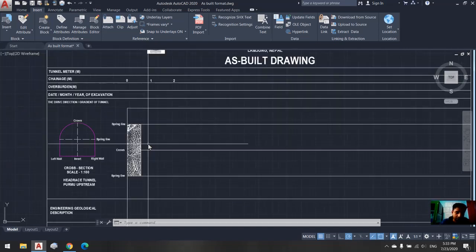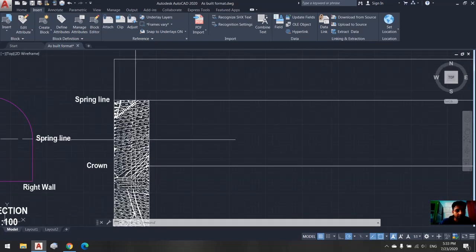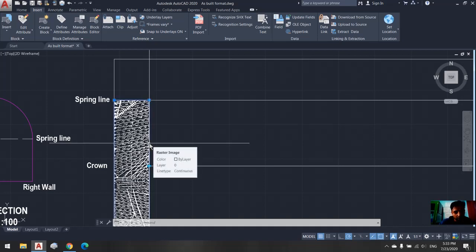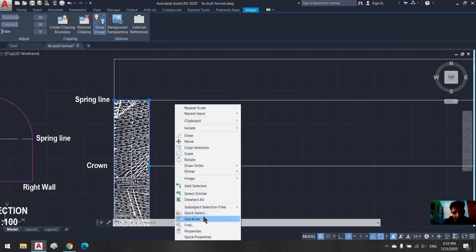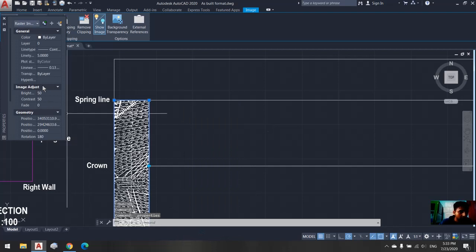The same way this is done now. So we have to overdraw. We have to draw over this map. So for this, click on the edge of the map, right click on properties, and go to transparency. Here it is written ByLayer. You can put any value from 0 to 100. So I'm going to put 40% of the transparency.